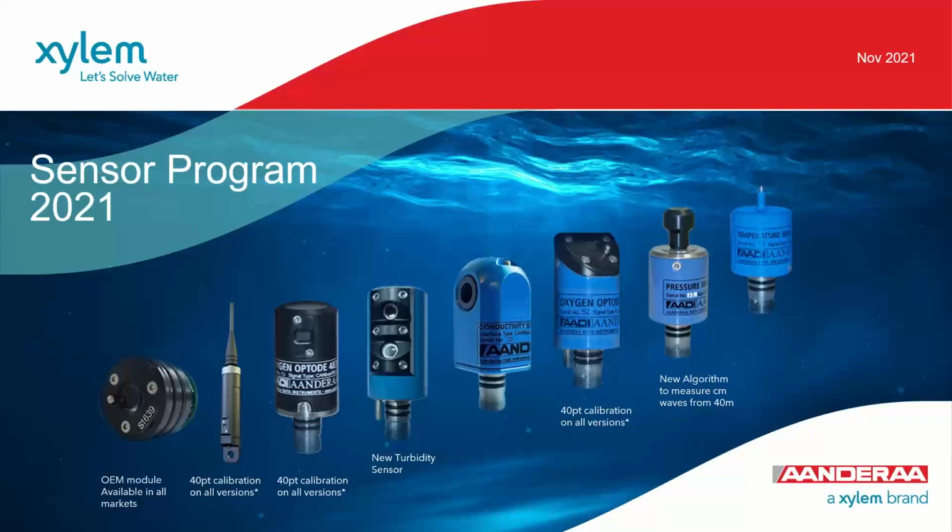To the lower left, we have an optode, which is our best-selling optode actually, but almost nobody knows about it, because it's used to integrate into cameras in aquaculture. And now we also start to offer that in other applications, and it's a useful sensor to integrate in many cases. It has temperature compensation just next to the foil. It's 40-point calibrated like the others, and it has 2 O-rings, so you press it into the body where you want to mount it, and then it becomes flush mounted.